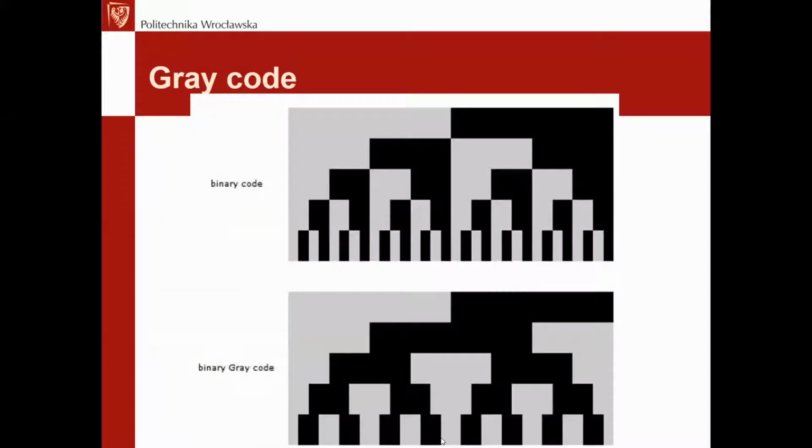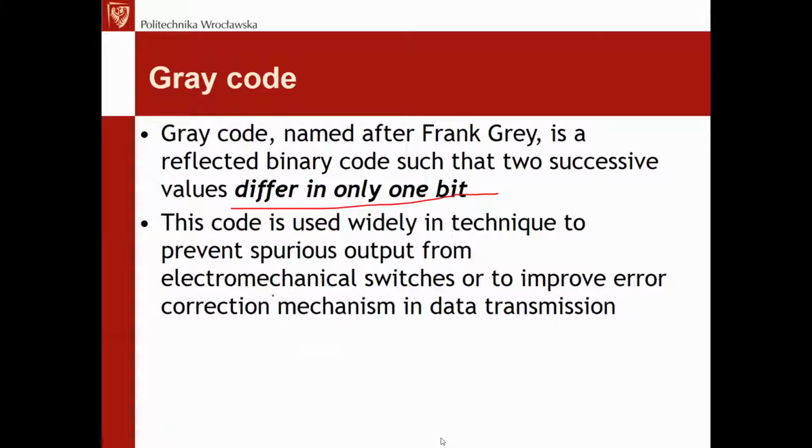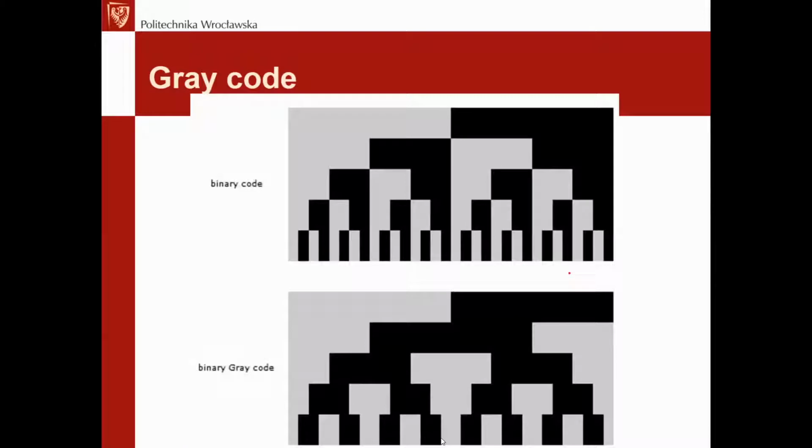But the idea of the gray code, which you can see here, and the reason it was introduced physically on the market, is to use it in various encoders or various devices. It's even written here, I think: electromechanical switches, for example, because we are reducing the frequency of changes.